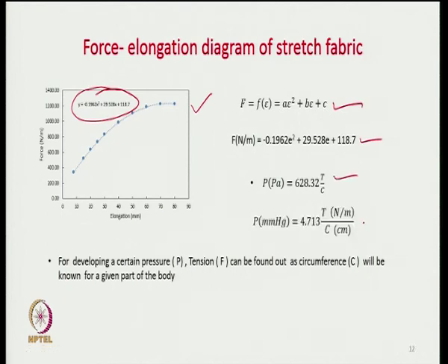These formulas were also given earlier; we are just repeating them again. This equation describes the force development with elongation. As the elongation increases, the force in the fabric increases and gradually it levels off. For a typical elastic fabric, this was the data that was obtained.